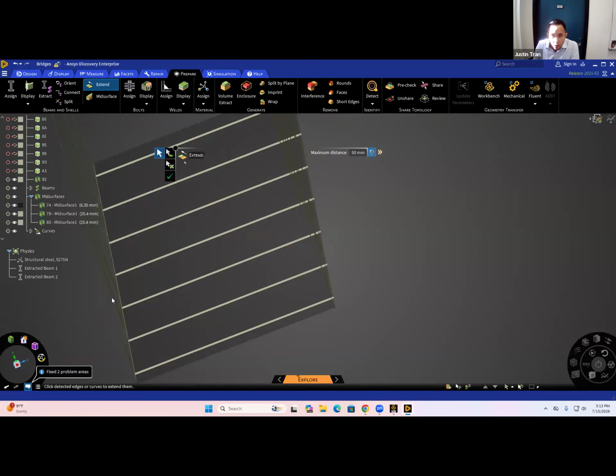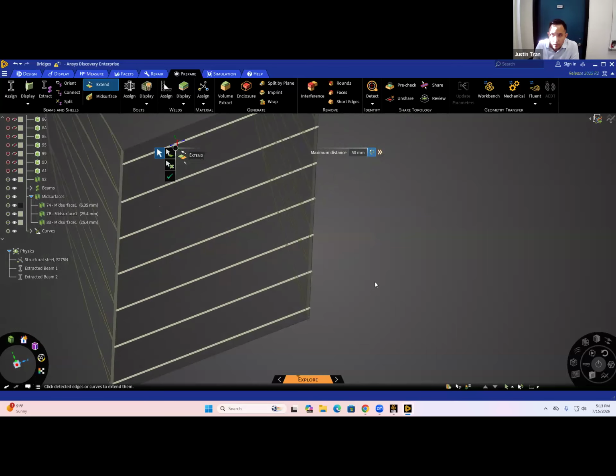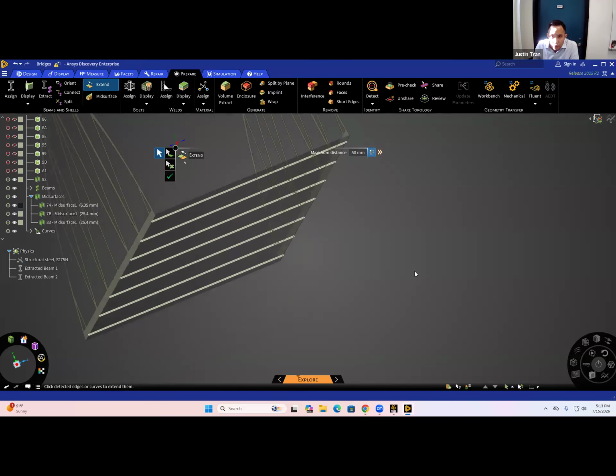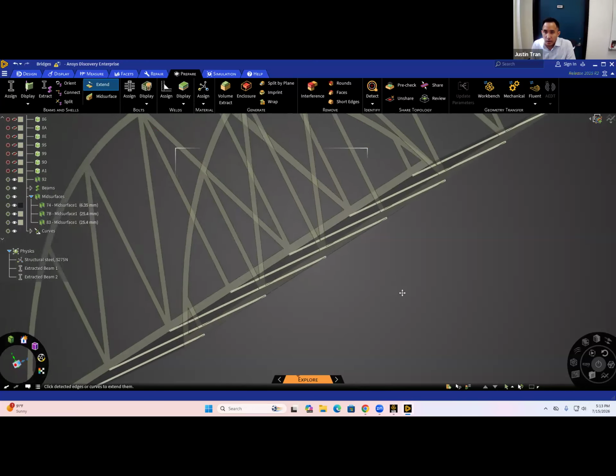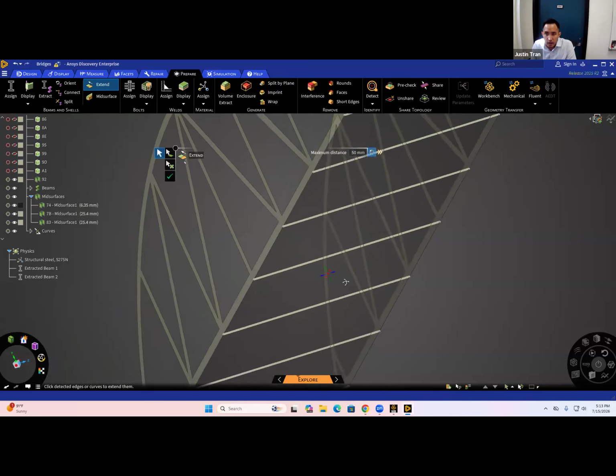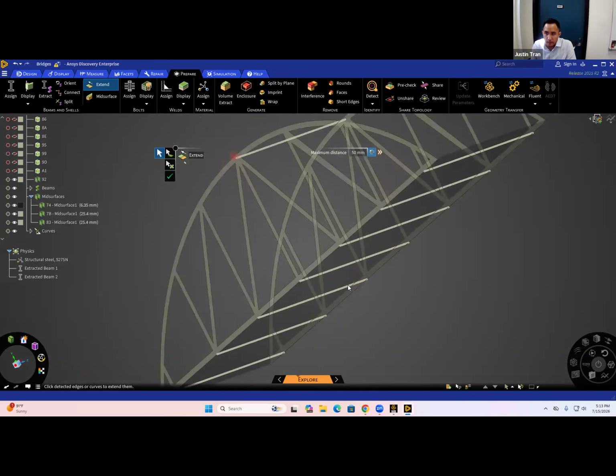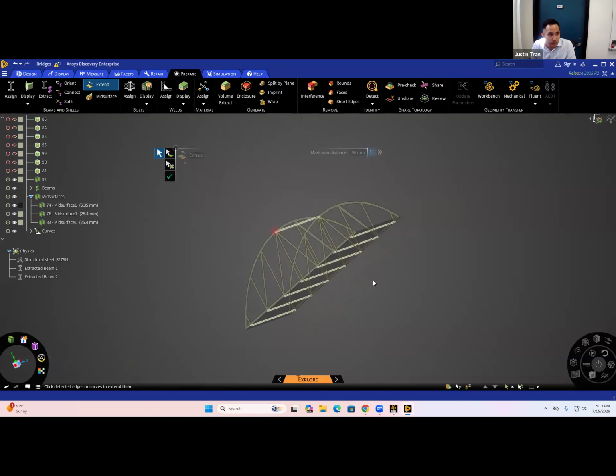You can see now that our road is fully connected to the sides of the bridge. If you did everything like this, then you should have your geometry fully converted to shells and beams, and all the gaps and alignment issues should be fixed. All right, everyone able to get to this part?